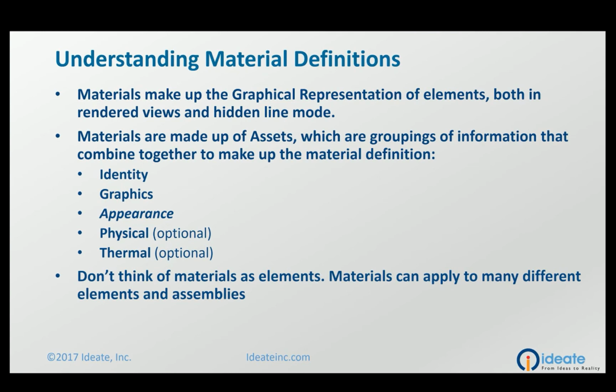So if you're not interested in doing any sort of structural calculations, like if you're gonna take it out to Robot, or if you're not interested in doing any sort of thermal calculations, you just basically wanna make it look good in your documents, both from a rendering perspective and documentation, you can actually omit these two tabs, okay? Again, graphics is what represents the documentation part where appearance represents the rendering, okay? So that's the whole thing.